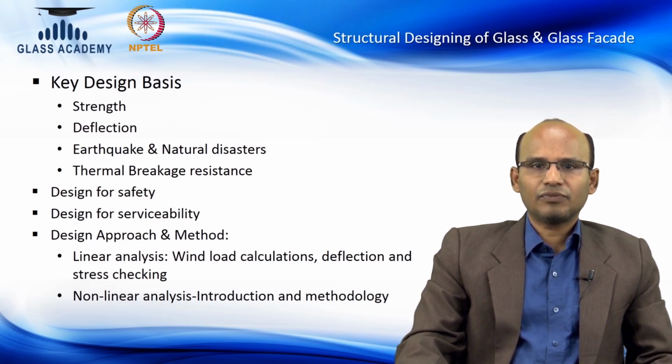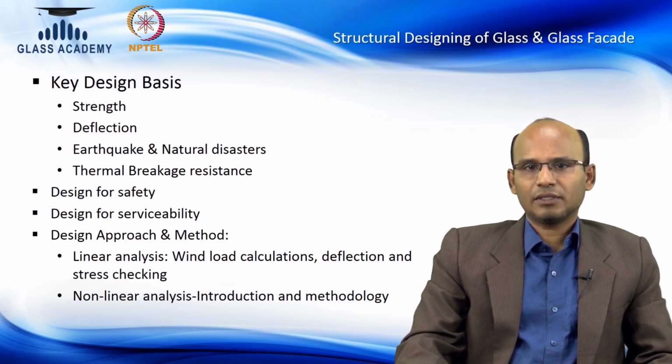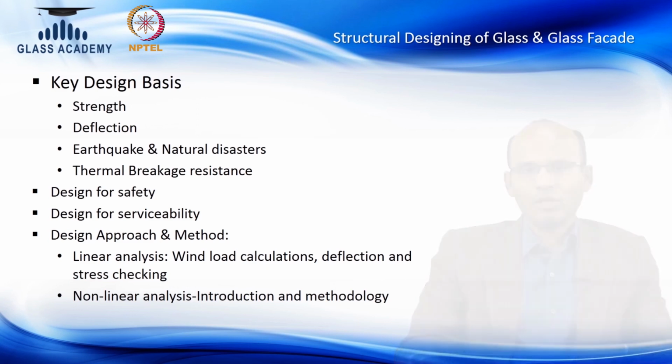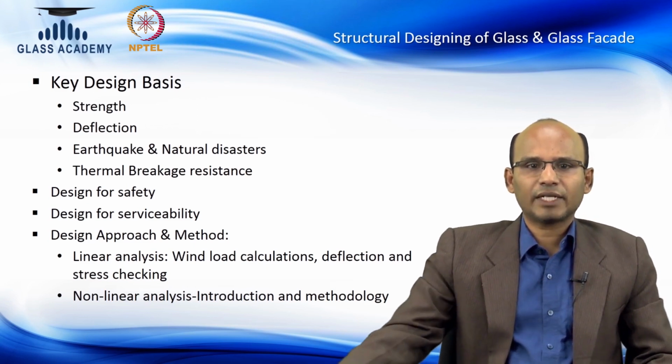So it should be designed for safety and designed for serviceability, and in the design approach, when we do the design, the factors are wind load factor, dead load factor, live load factor. Different factors are considered with suitable combinations, and in some instances the design needs to be checked for non-linear behavior. Non-linear is critical if you are doing slender elements, small size glass fins used for large spaces. If the slenderness ratio is too small, then the slenderness factor is critical.